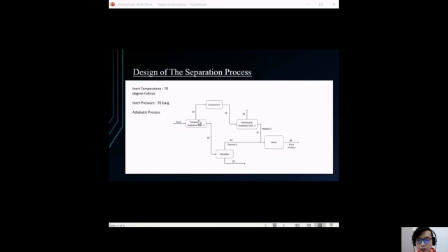The feed will enter the first membrane separator unit, and all the water vapor is assumed not removed by the membrane and transported into the absorber for water vapor absorption. Then we will get our first product at stream 4, and excess water vapor will be removed from stream 9. Besides, the compressor is used to increase the pressure of the permeate for the second membrane separation.